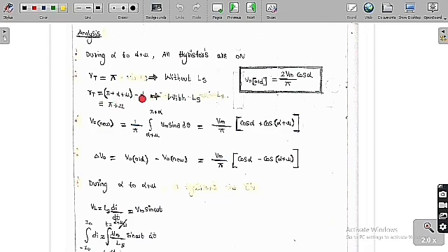If you take the difference, we get pi plus alpha plus mu minus alpha, which is pi plus mu. So this is the conduction angle of each thyristor with Ls, which is pi plus mu. So it was increased. The conduction angle was increased by mu by adding the source inductance. So now, what is the average value of the output voltage?